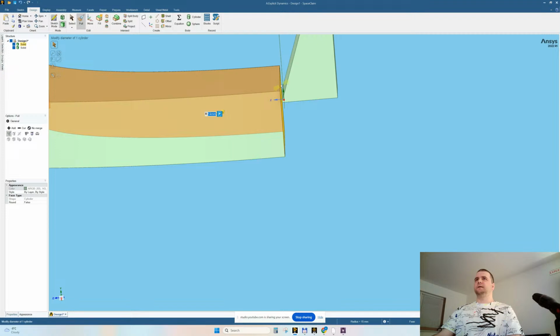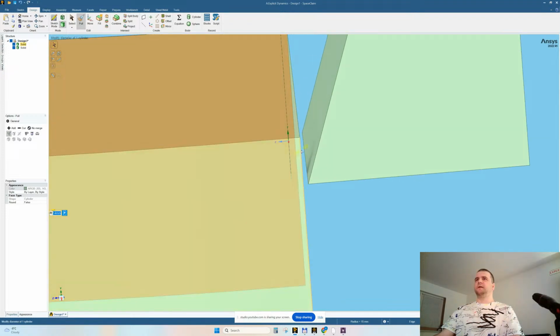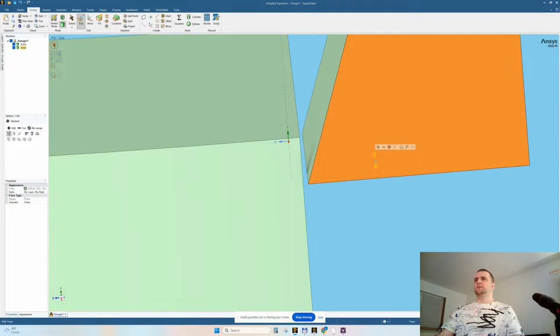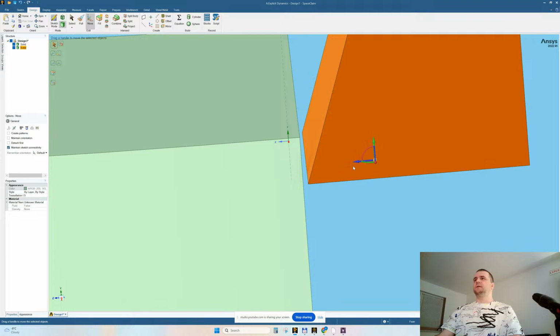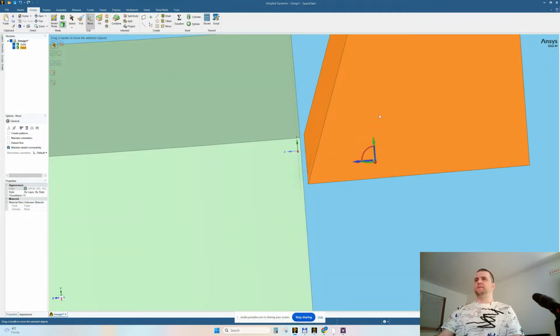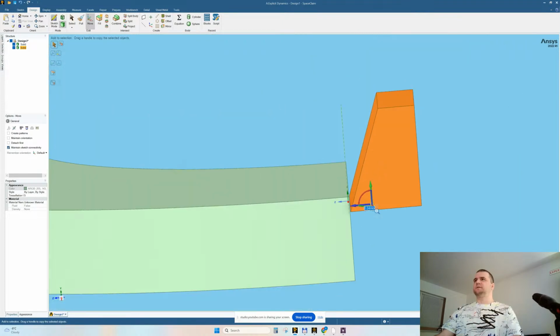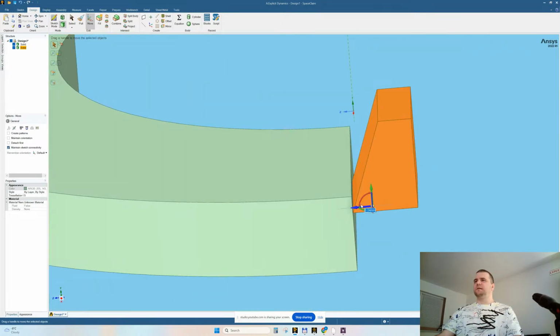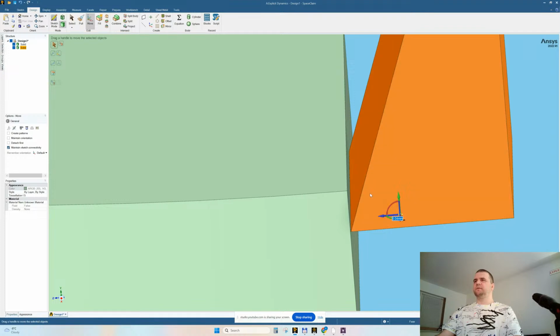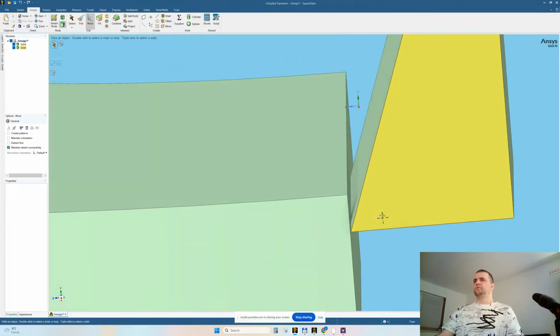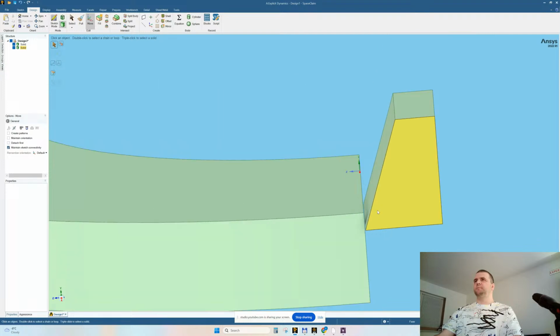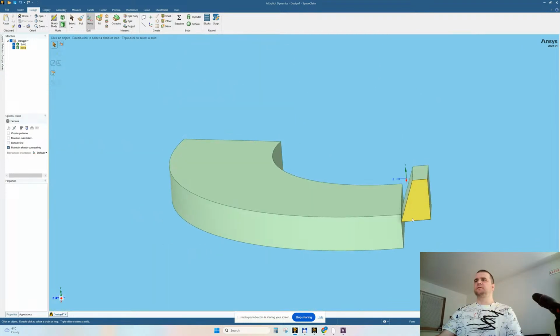I said that I will leave it live edge. If we leave it live edge, we'll have a very nice, very coarse hex mesh. If we round it, then we'll begin to have more elements and maybe get out from the hex meshing.